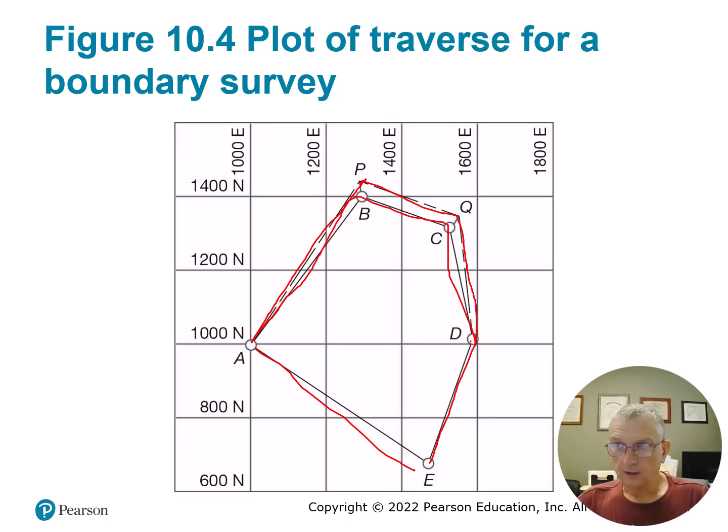Now, I believe they skipped over computing final adjusted traverse lengths. We're basically going to be taking the latitudes and departures back. So we'll divide. We'll take the latitude and departure, the square of those. Once we get our adjusted coordinates, we'll take the square of those, take the square root of the sum.